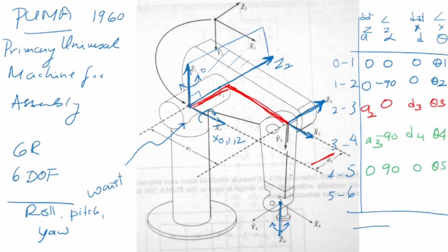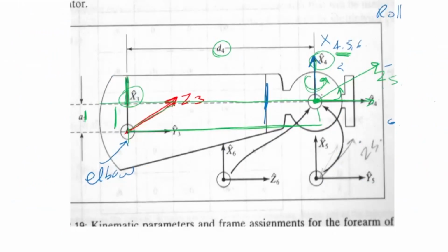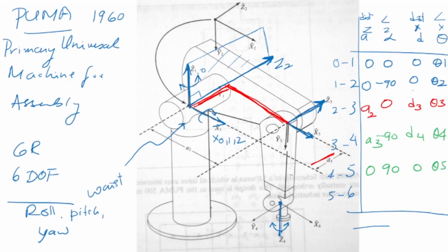Now what about z5 and z6? Z6 has come back this side again, that's my z6. So z5 has rotated clockwise about the x5 axis and has become z6. So this basically means that this angle is going to become minus 90. It is 0, 0 and theta 6.